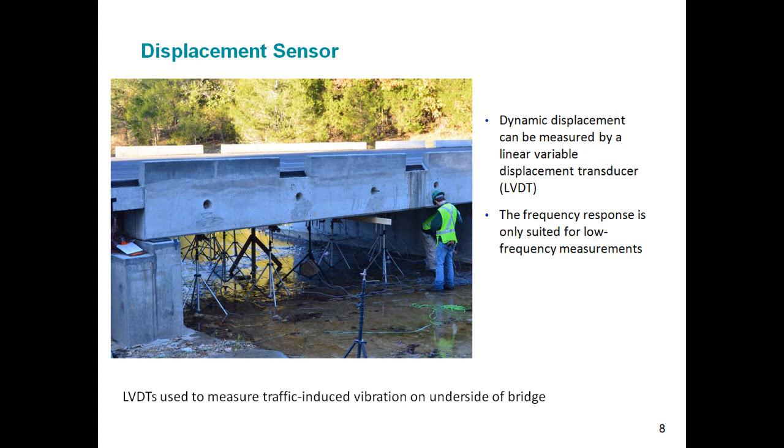But if we have a small electronic box, an avionics component with a circuit board, then that most likely would be subjected to higher frequency vibration with a corresponding higher frequency response, and the LVDT would just be impractical for that case. But they're great, for example, for civil engineering structures.